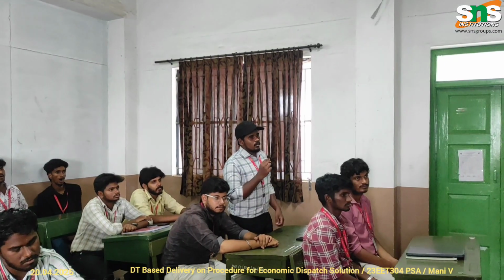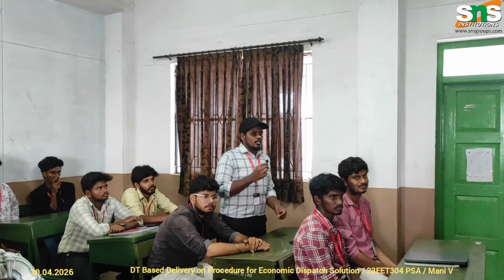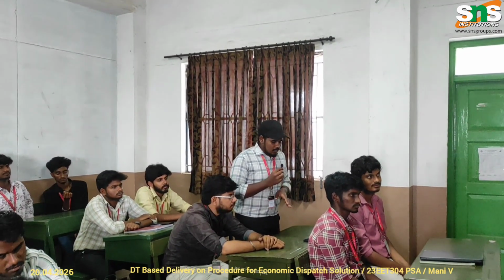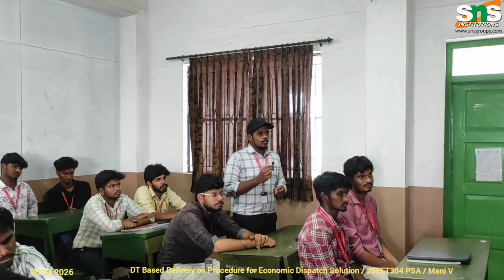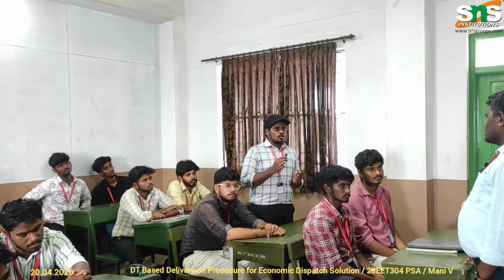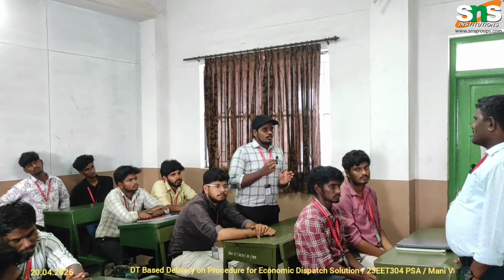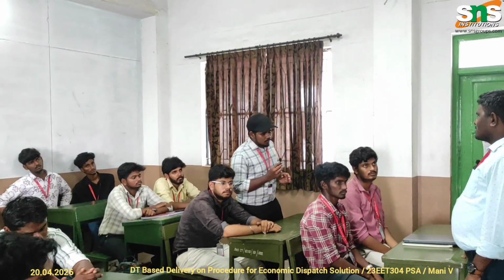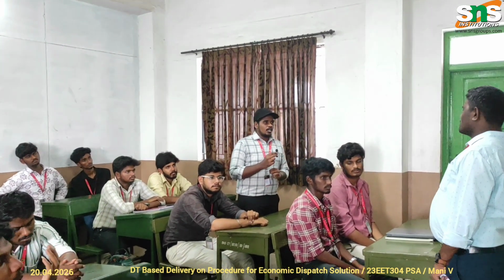Conclusion. First, find all PGi values and check the minimum and maximum operating limits of each unit, and substitute them in the fuel 1, fuel 2, and fuel 3 cost functions, and then find the total fuel cost. This method is called optimum economic cost.